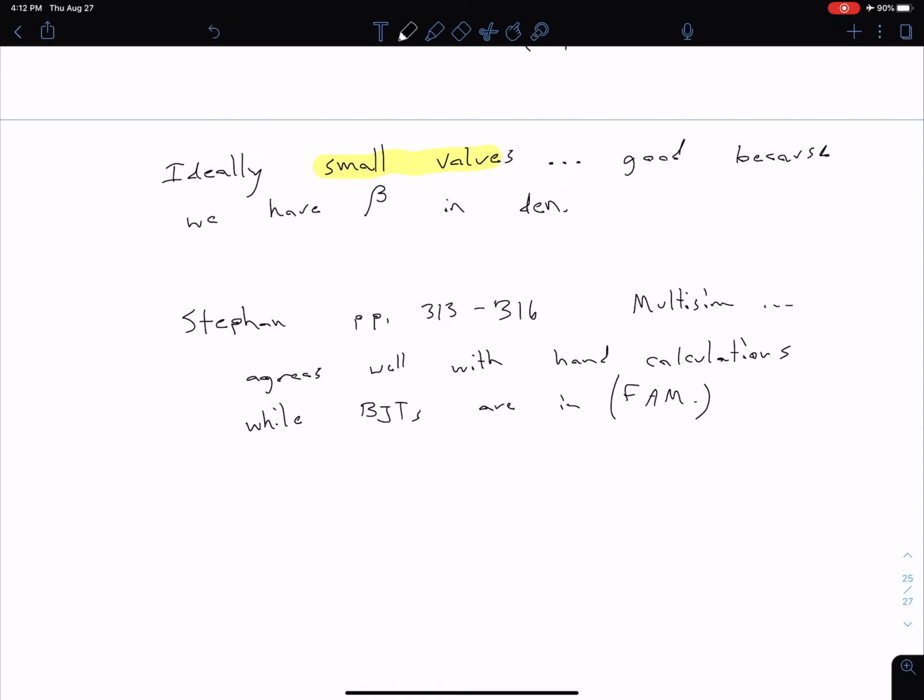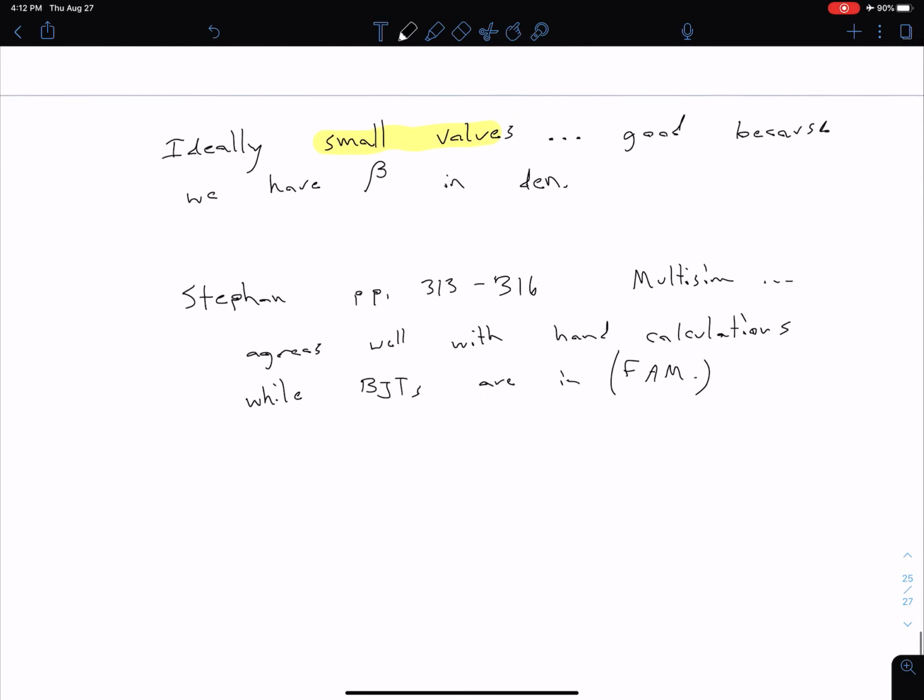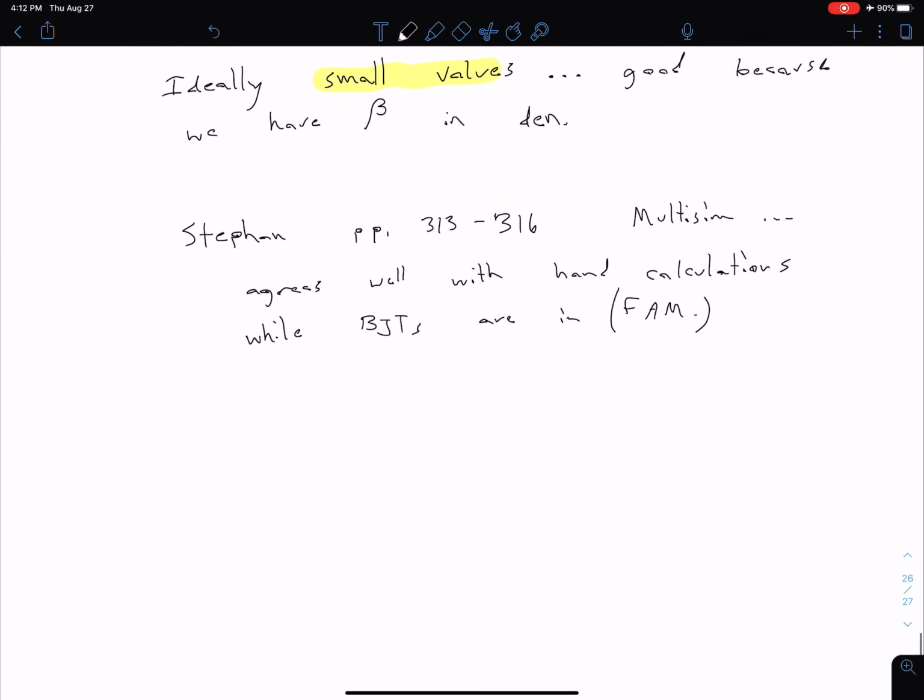A couple other design notes to keep in mind as we're considering this circuit is we want to consider our power consumption. We talked about this is a series pass regulator, and what that means is any difference between our input and our output power, so our V raw and our V out side, is going to be dissipated in that series pass device.